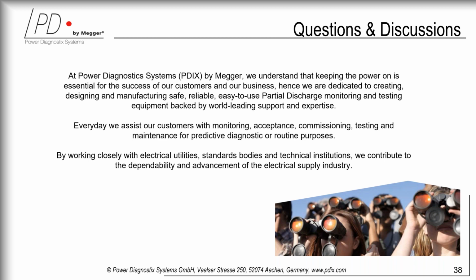So again, we are testing very carefully these bushing adapters. They are made out of aluminum, they have a gold-plated contact, and then they have a seal, and they are properly screwed into the system. Now, I have to tell you that the voltage that generally is found at this bushing adapter is somewhere around 10, 15 volts, depends on the bushing.